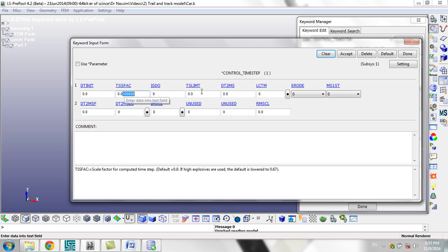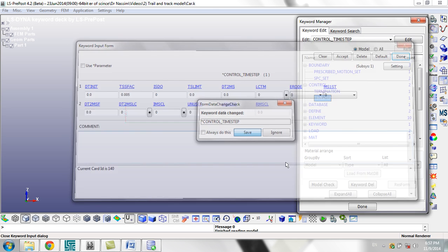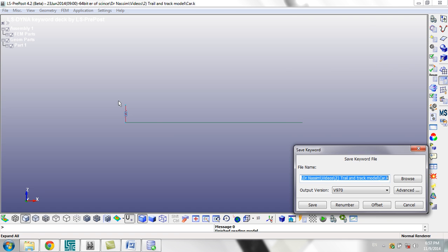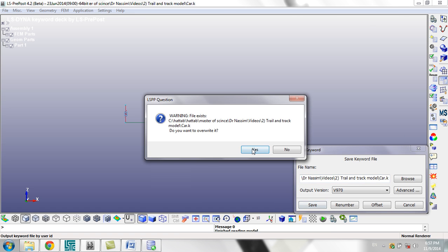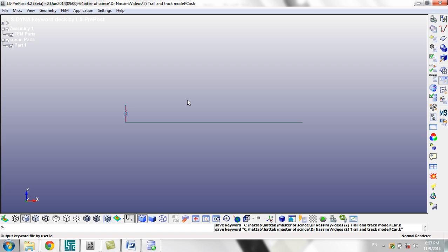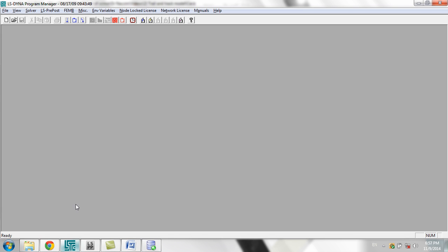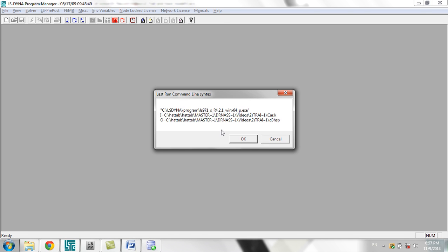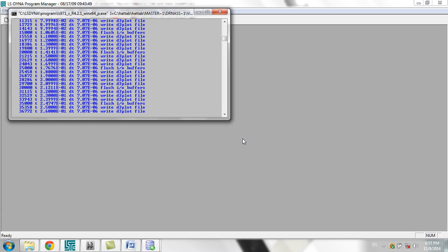and this time I'm going to decrease the time step again and make it 0.005. And then let's run the model again and see what we will have. For sure it will take a longer time. It will be twice the time that we spent previously, because we decreased the time step to half of the previous one, but hopefully we will have very good results.